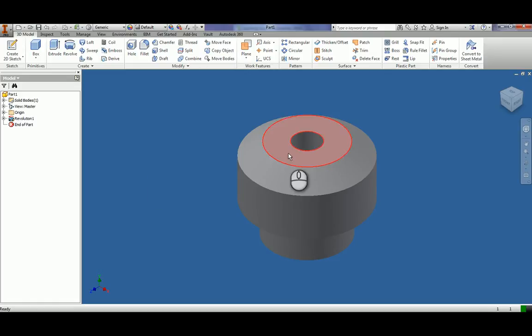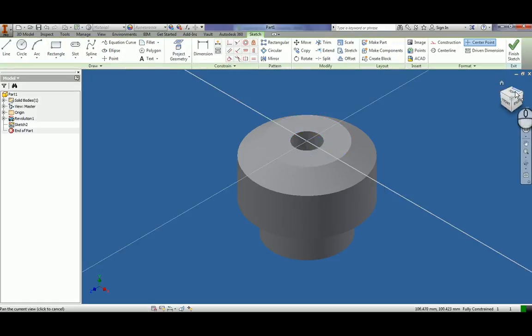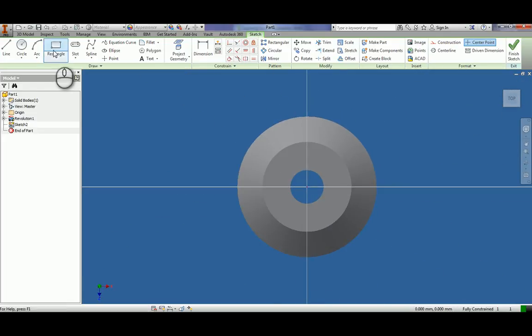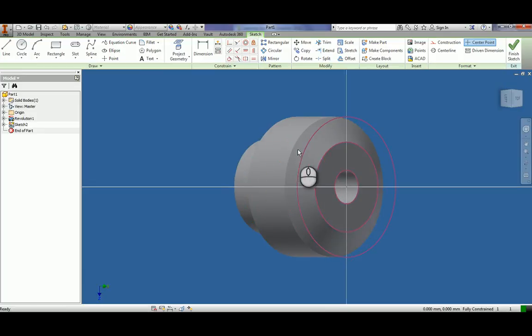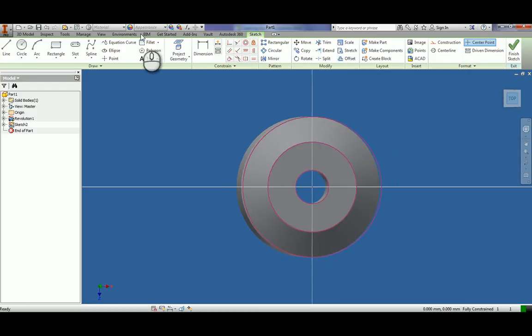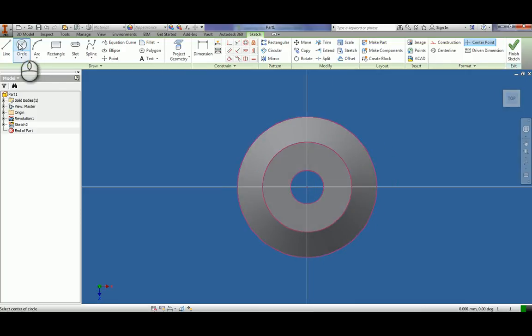But right now we're going to click on this top face, click Sketch, it's at top, and you're going to draw 2 circles after you bring up the project geometry. I'm just going to try and have everything up. What this does is it brings the dimensions and the sketching from the back to the front. So you'll notice how this line for this sketch is the exact same dimensions as this leading edge of the object. So it allows you to sketch on top of something where you may not necessarily have the original sketch from.